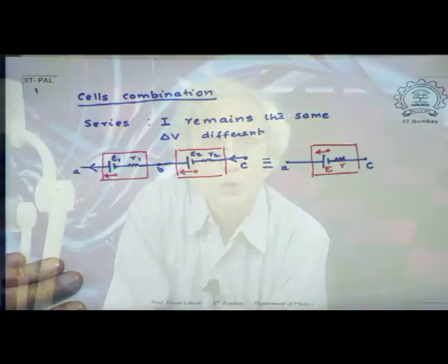Later on today, when we discuss the general rule for finding out current, we will realize that it is immaterial what your assumption regarding the direction of current is, because if you have made a mistake in the beginning and your answer turns out to be with a minus sign, it simply means that the direction of current is opposite to what you have assumed to be true. So let's look at that.